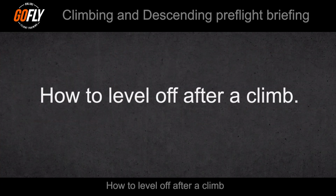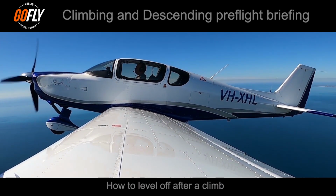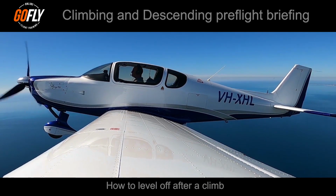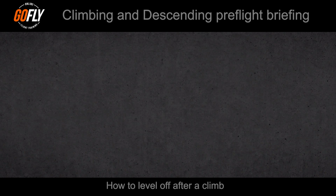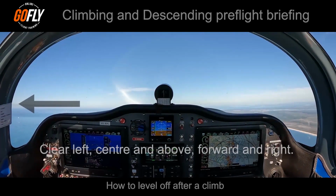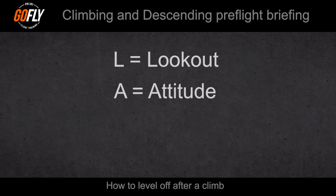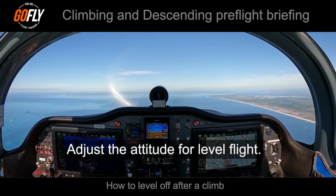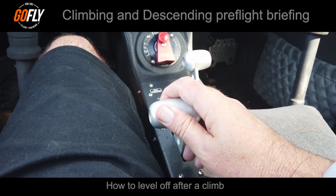We'll now demonstrate how to level off after a climb. Leveling off after a climb is the only climbing and descending sequence that is different from the others, and therefore the acronym is different. The acronym for leveling off is LAPT. L is for lookout for other aircraft. To look out, we check left, center above, forward, and right. A is for attitude. Adjust the attitude for level flight. P is for power. We reduce the power to the cruise power setting.